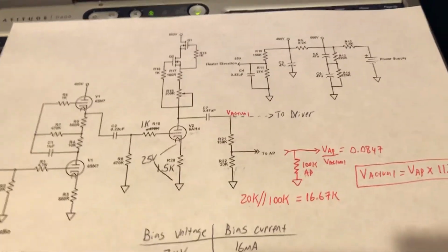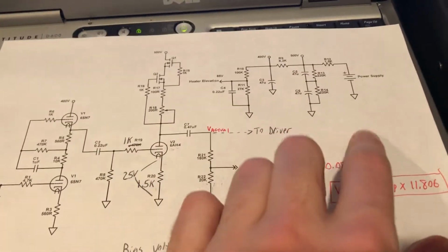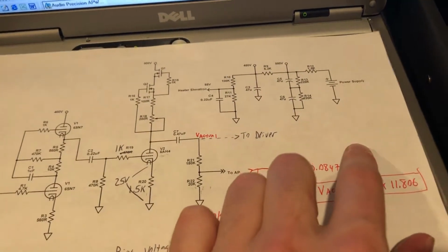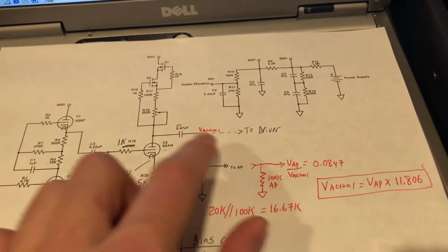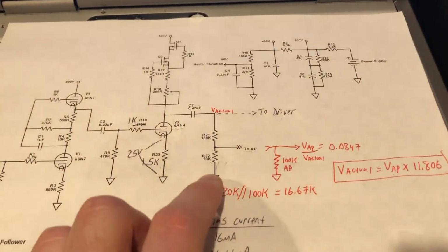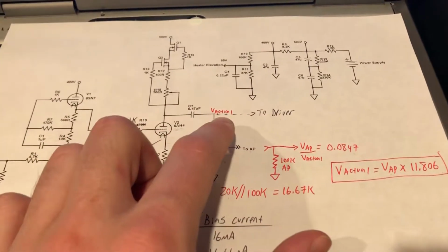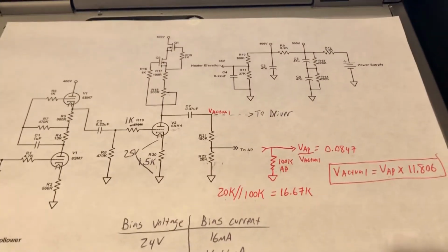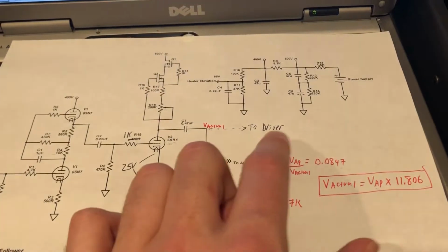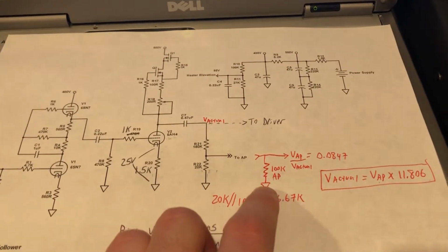And I guess this also highlights why the driver is so important in front of an 845. An 845 is a difficult capacitive load. You'd have all these exact same issues: poor bandwidth, poor linearity, lower than expected voltage gain if we connected this directly to our 845s. And that's why we were not going to do that. We're going to buffer this with a driver, and therefore we can then drive our 845s just like we can then drive our AP accurately.